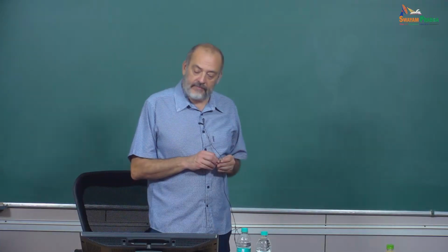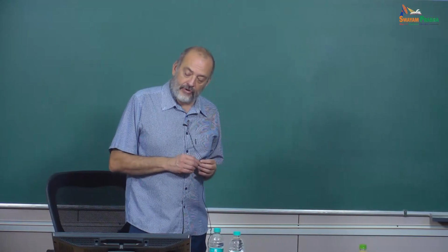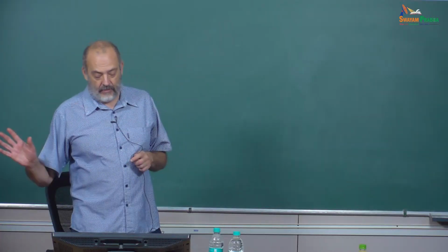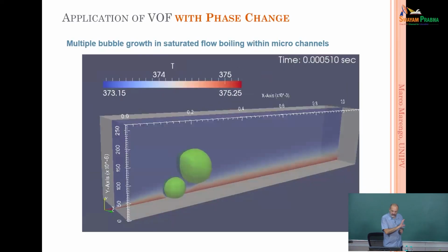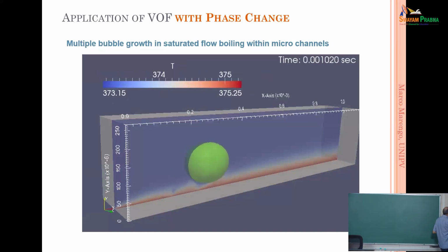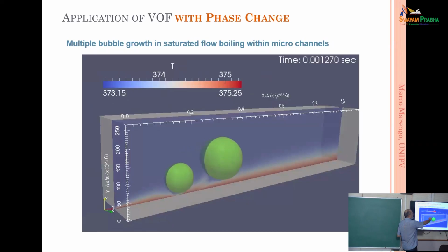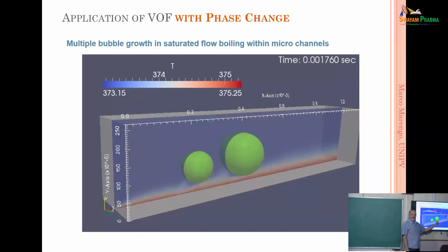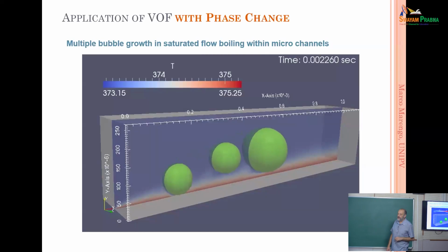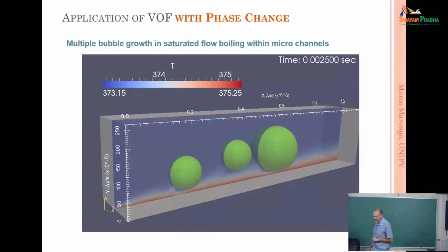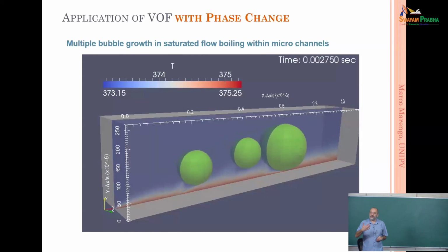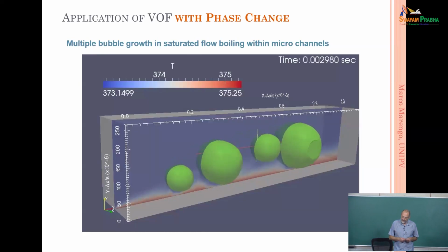And this is, for example, the formation of a bubble inside the channel. There is a little bit of flow from the left to the right, and we are forming bubbles. The bubbles are growing, and then they are going in the flow. Of course, this is going to decelerate because of the drag, and so the other one is going to catch the first one. So we have this kind of situation where we have the classical generation of a slug flow, with Taylor bubbles inside.